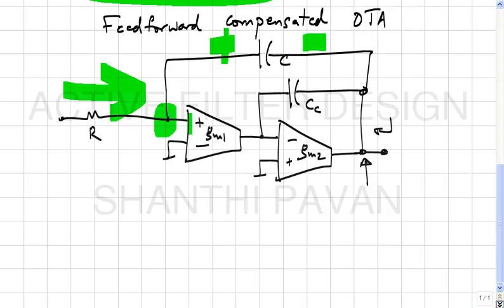The output voltage is the negative of the capacitor voltage plus the virtual ground voltage. Is that clear to everybody? It would also be exactly the same as the capacitor voltage, because the virtual ground voltage is 0, which means that the output voltage would be nothing but minus the integral of the input. So, all non-idealities that you see at the output can be traced to the virtual ground node not being 0 as a function of frequency. It is not just enough if it is 0 at one particular frequency; identically, the virtual ground node must be 0, right. In the single stage OTA, what did you find was the virtual ground voltage?